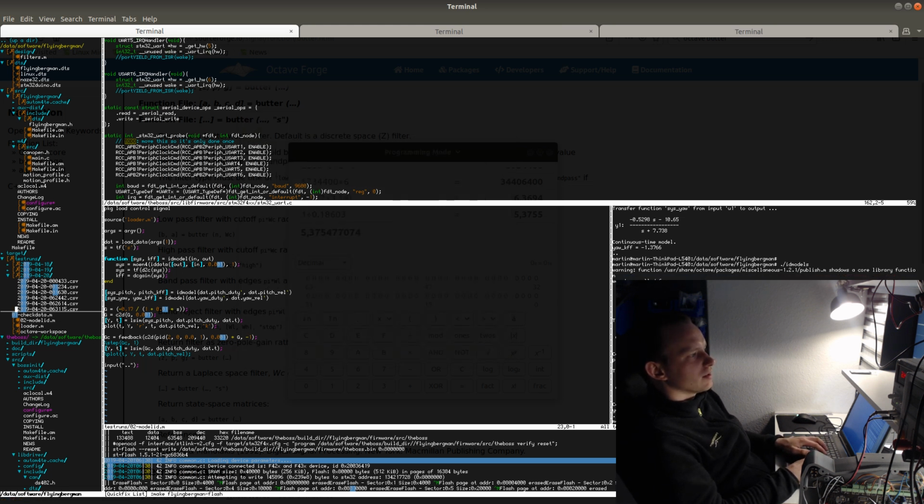So now I can take this transfer function, the transfer function g, and I can use the feedback method and the PID method in MATLAB to create a transfer function for the combination of the controller and the motor.